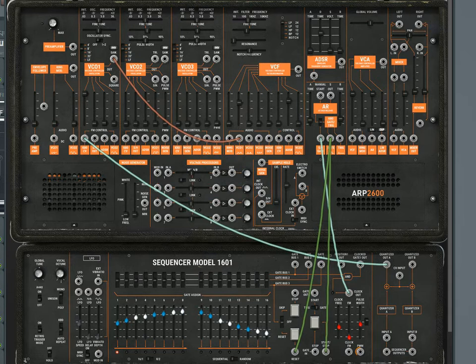With the current settings, though, we'll find that this slider has no effect whatsoever. I'll start the sequencer again. I move the slider up and down, and nothing happens. Why is that? Well, first let's move this slider back down to 0. With no controller signal patched into this input jack, the FM slider is taking its directions from gate bus 1. That's this line right across here, the top line in the gate buses.